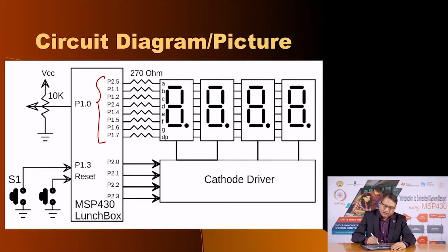And then we are turning one digit on, displaying the information there, then we are turning this display off, then displaying the second digit and so on and so forth. And when we reach the last digit, after that we come back to the first digit. And if we did this exercise fast enough, fast enough to beat the shortcoming of the human eye, that is the persistence of vision, if we multiplexed these displays faster than the persistence of vision limit of the human eye, you would see that all these displays are on at the same time. While we are multiplexing the display, what do we want to do?